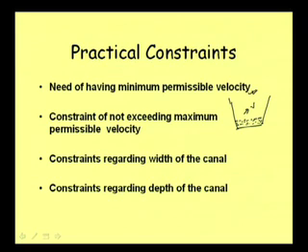That will create problems. In fact, in an area in a city, I was involved in a drainage design, and I could see that the existing canal could not serve because, say, the total depth is 1.5 meter, but the depth of sediment that was observed is 0.5 meter.